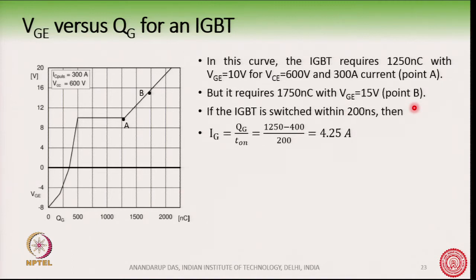The area under this curve is about 1750 nanocoulomb. So, this much charge will be required to turn the device from the fully off state to the fully on state.